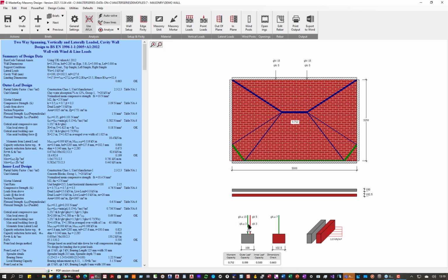It shows it on this side. It would probably be more realistic on that side. It doesn't really matter from an analysis point of view, but that is the eccentric loading from this level, such as the floor and the live load on the floor. And then the outer leaf has just the self weight of that upper leaf. And yes, in our first wall we were still taking the self weight of the wall itself. Of course we were. It was one of the inputs.